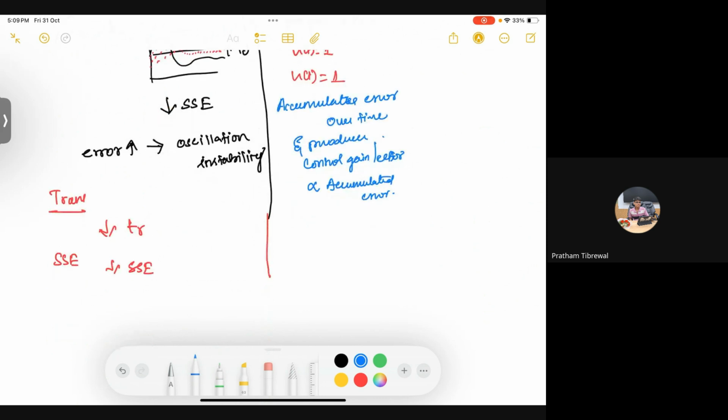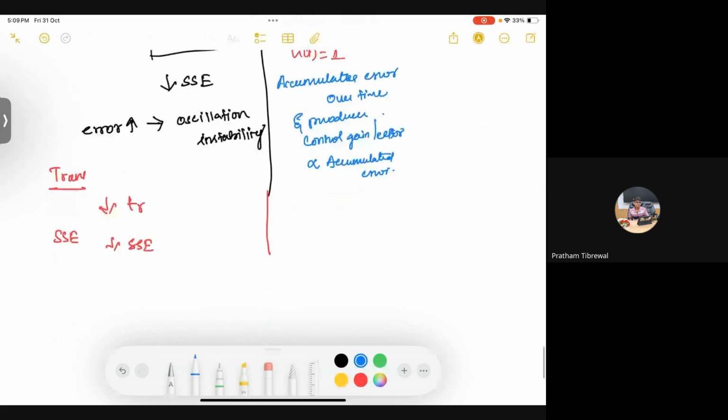This is particularly very useful when the proportional controller, whatever value you use, couldn't reduce the steady state error to zero. Sometimes this proportional controller alone cannot make the system come to zero steady state error. There will always be a steady state error because it has been changing proportionally from one point to another point. After some finite iterations, it won't be able to bring out the steady state error at all. So at that point, adding this integral action would help.